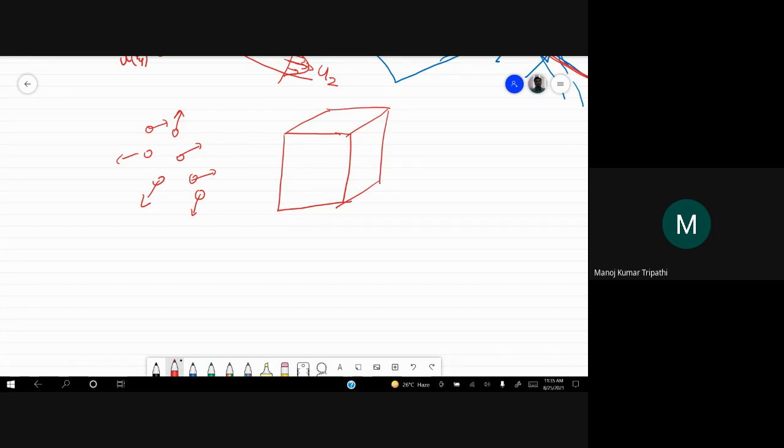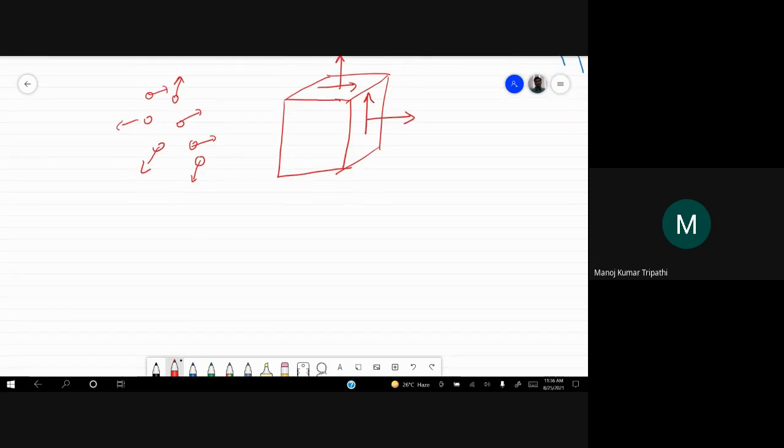So on this surface you have some forces. Let's say this is a shear force, this is another shear force, this is a normal force, that is a normal force, and so on. So you can write these forces as tau, let's say this is tau xx. So there is some equation which relates these forces, tau xx, with the velocities inside this fluid domain.